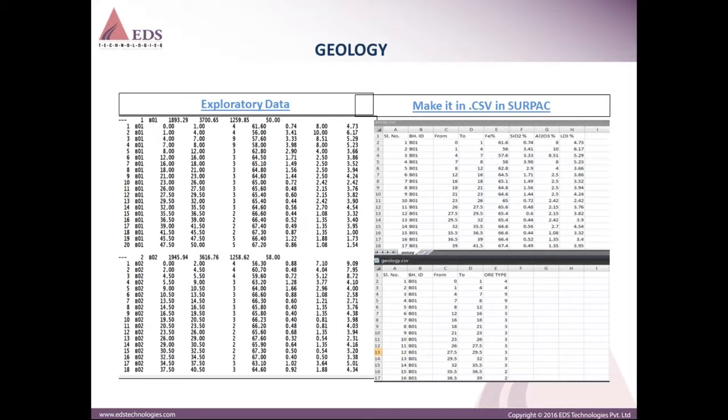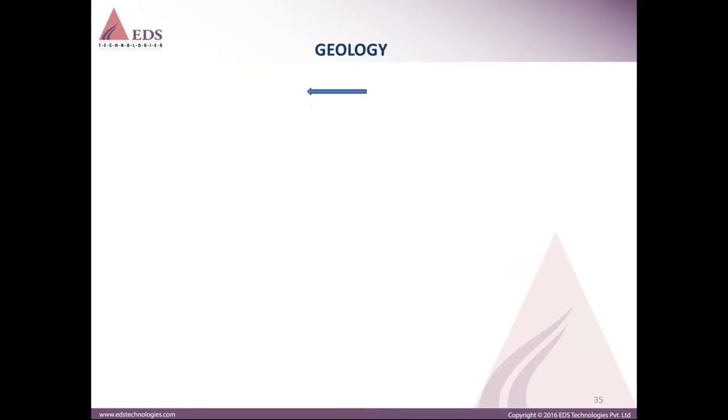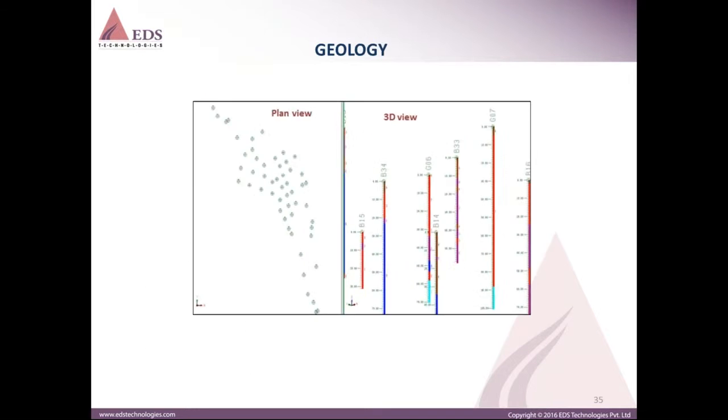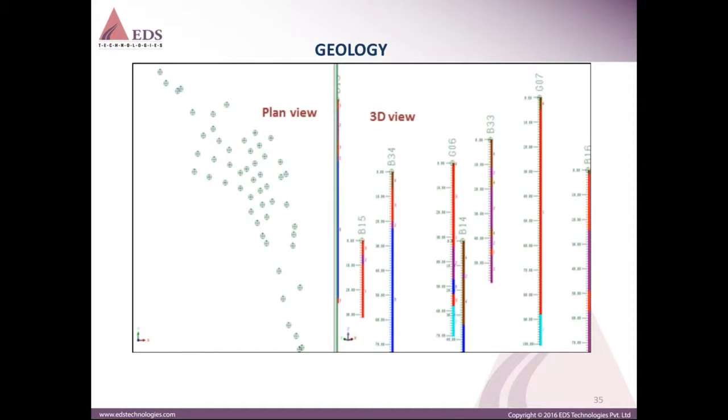And this is an example: on the left side you can see the raw exploration data, and on the right side you'll see the data managed into a CSV format so that it can be imported into Surpac. Once it's imported in Surpac, you can utilize your boreholes both in a 3D graphics window or in a plan view also. And these boreholes are colored based on the color coding of the lithology.